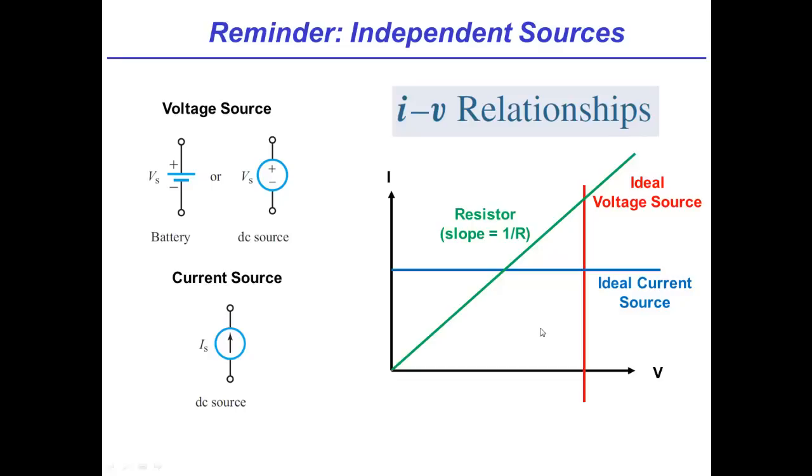So on this plot, you see one for a voltage source, a current source, and a resistor. We can generate these sorts of IV plots for all the types of electronic devices that we use. That's right. And it's both useful for getting an intuitive feel of how it works. You can see maybe a nonlinear device, which would have some strange characteristic in an IV plot. And it also, in some cases, is a quick tool for finding the solution of how a couple of devices together might work, because you can graphically plot both of these things and look for, say, intersection points. But that's something we'll cover later in the course.